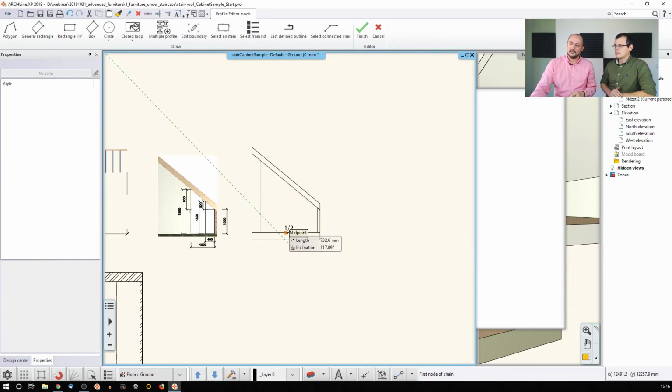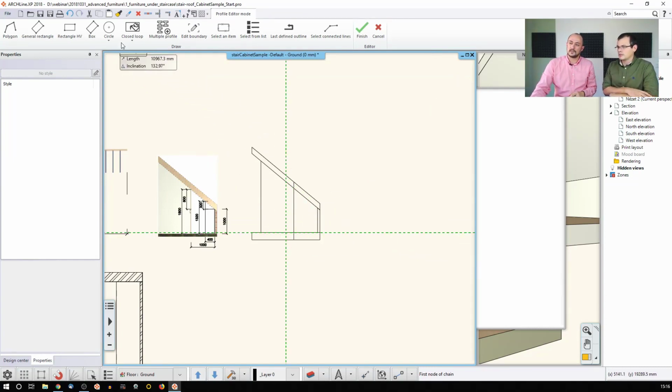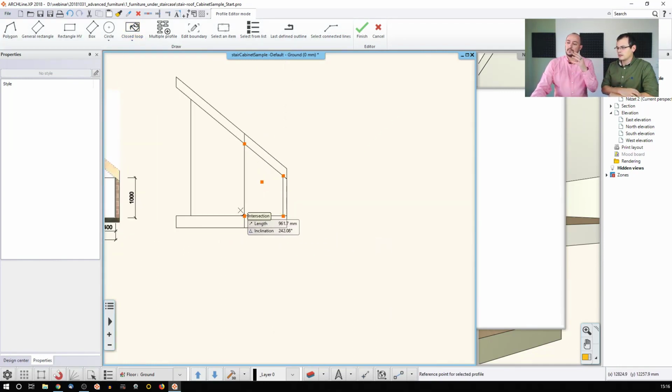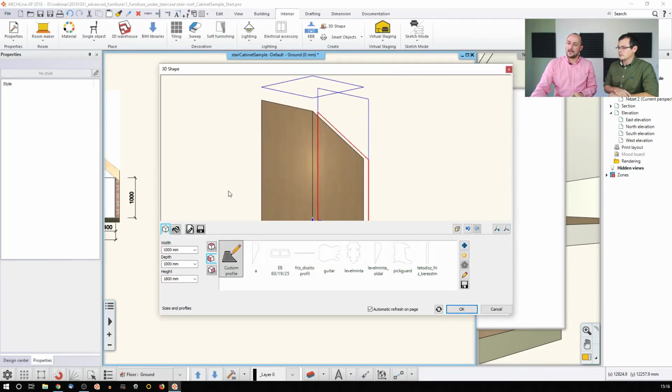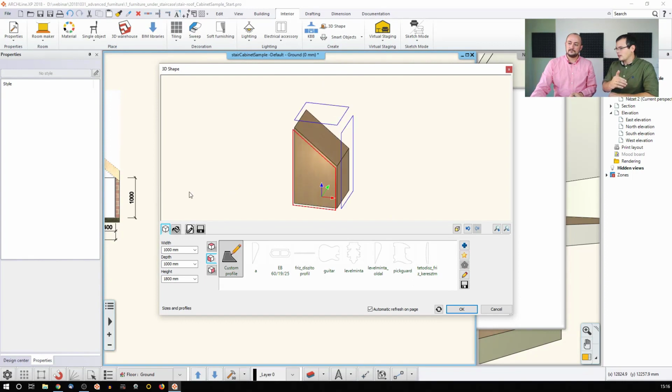And then now I can track it, and I don't even have to click on the contours. I can just pick up this loop, and then it automatically recognizes it. Let me just pick up, for example, the left bottom corner as a reference point, and now I end up with this. Is it long enough for the purpose that you want to use it for? Not now, but I can either define it as, I think that was 7 meters or something like that. I can use that.